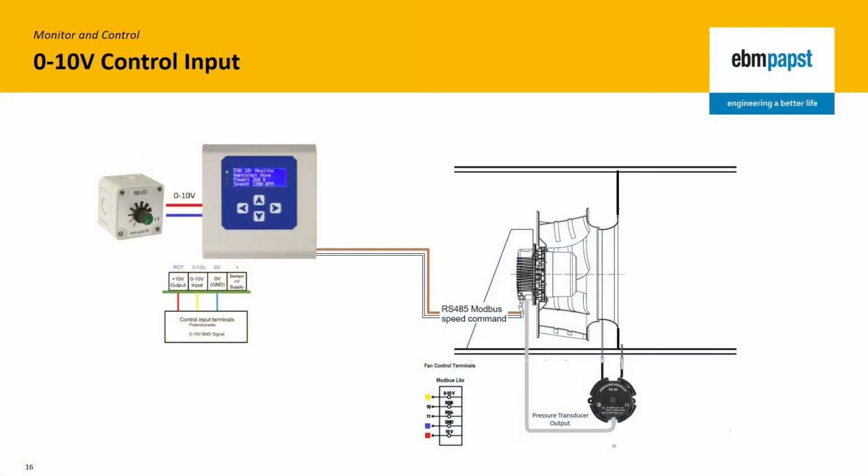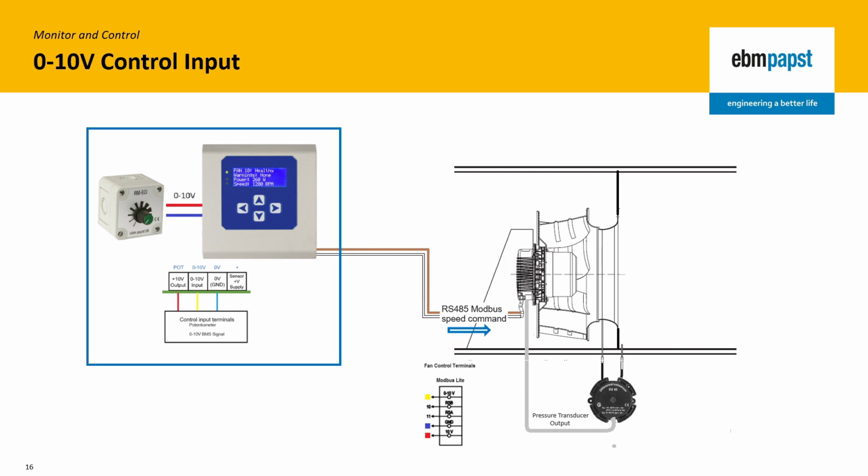In the next example, we will configure the MDC controller to respond to a 0 to 10 volt control signal input, convert the analog signal into a RS485 speed command, and read the sensor output of the transducer from the Modbus register that monitors control input A-in-1 on the fan.